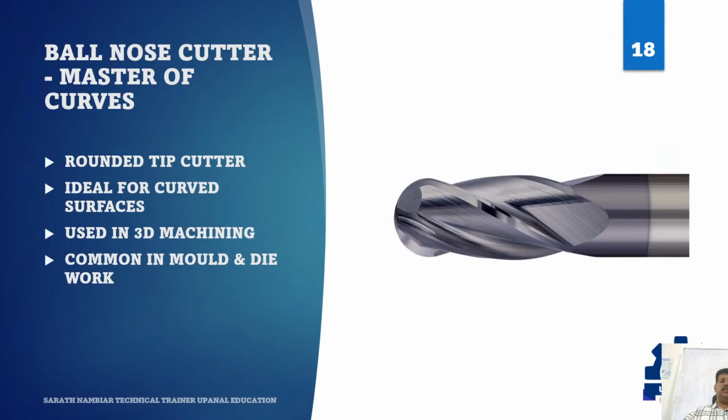Next is the ball nose cutter. Here we are moving from flat geometry to curved geometry. This is a ball nose cutter. Immediately when you look at the tool tip, you'll notice that the bottom is rounded like a half ball. This rounded geometry changes everything. This cutter is not mainly for flat pocket floors. It is for shapes, contours, or flowing surfaces.